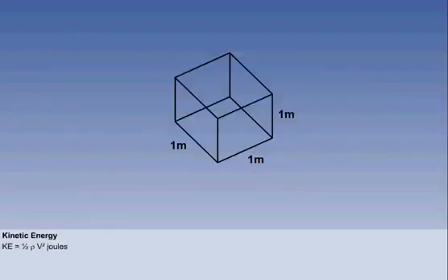Let us consider the kinetic energy of 1 cubic meter of air moving at a stated speed. It is the product of the local air density, ρ, and the square of the speed in meters per second, divided by 2. If this cubic meter of air is completely trapped and brought to rest by an open-ended tube, the total energy will remain constant, but by virtue of being brought completely to rest, the kinetic energy is converted to pressure energy. This pressure energy is, for practical purposes, equal to half the density times the square of the speed, usually referred to as half rho v squared newtons per square meter.